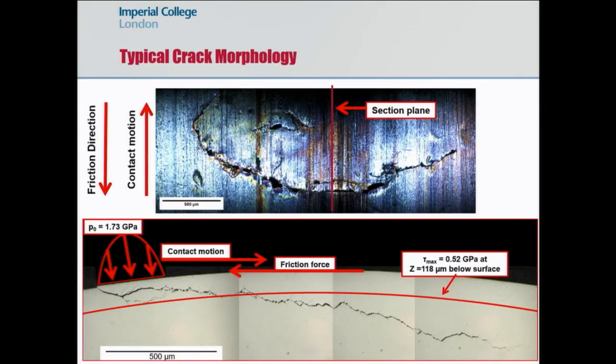Well, let's take one of those big cracks. We can control the propagation rates now using this methodology, so we can propagate them long or short or whatever. And here's a cross-section of that very long surface crack, and you can see some interesting things. It's gone quite deep into the subsurface, similar to that helicopter one you saw earlier. We've got some zigzagging here. You have an angle that's changed after the initial initiation of the surface.